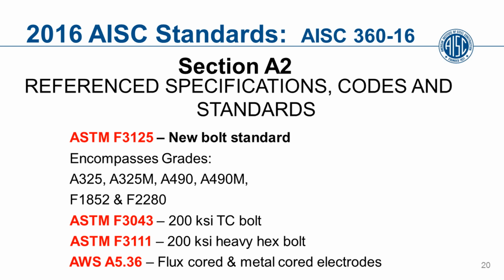One example I give is I always thought when I first heard about these bolts it'd be great in bridge construction, but bridges are subject to a lot of corrosive environments and there's a lot of moisture in bridge areas, so they wouldn't be really suitable for that application. But they would be suitable for maybe some large truss connections in enclosed buildings.